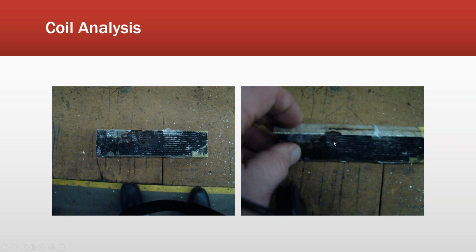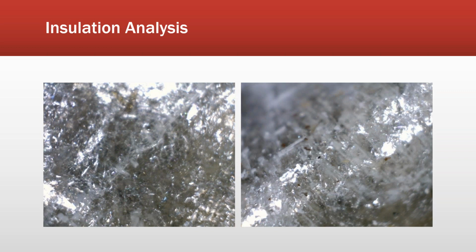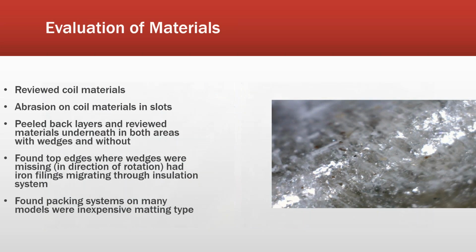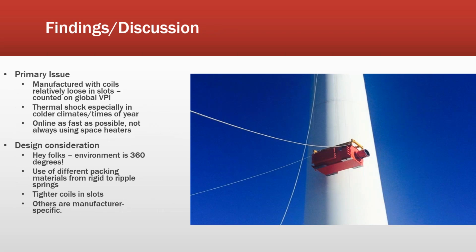We'll see a winding stress signature. I published that in IEEE year before last, and it's basically a turn-to-turn short, or shows like a turn-to-turn short. These are just pictures of the termites working through that insulation with a 10 power microscope and some of the arcing that occurred. In any case, that would happen. Well, it's detectable. So before the winding fails, we're seeing insulation related issues. That, by the way, is the generator that had the catastrophic failure of the winding that I showed early on.